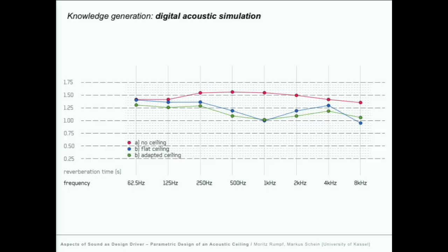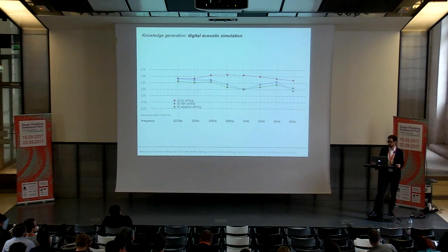However, we also did try some after-the-fact simulations with already more elaborated designs to analyze whether it can benefit comparing variations and predicting the intervention's performance. Here we found that the realized ceiling in the end outperformed the simulated one significantly. This shows that a meaningful prediction can only be made when absorption coefficients for all the materials are known in the specific installation situation.